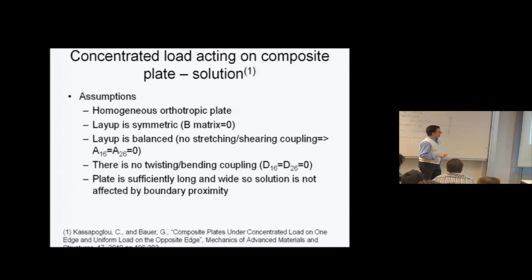We mentioned last time, I believe, that if you have anti-symmetric layups or layups using only 0s and 90s, or I'm telling you now, layups using only fabric material, plain weave fabric preferably, then the D16 and D26 terms are 0.